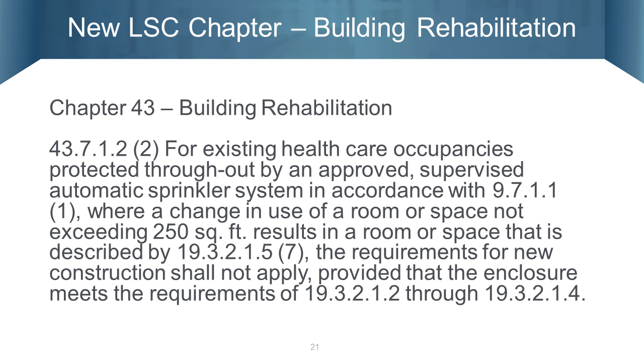So we have to look at the existing healthcare occupancy chapter and look at a hazardous area and see what's required there. You'll see that it does not require a labeled door. It's simply a substantial door with a closer. And if you're sprinkled, it does not require 1-hour rated walls deck to deck. So this is a huge benefit for us in existing healthcare.